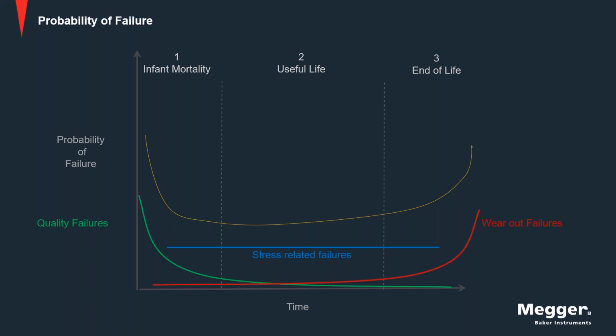So it's important to test during that infant stage. When you receive that motor in, when you go get it from the warehouse, make sure you test it there. You get a baseline, put it in to the application, test from switchgear. Now you've got a baseline for that motor.